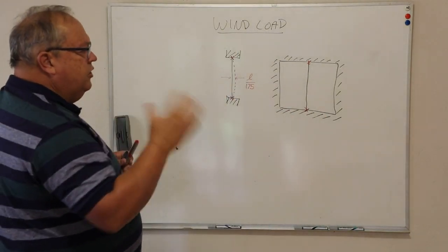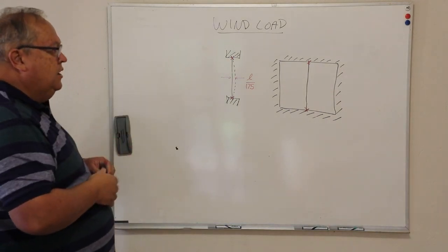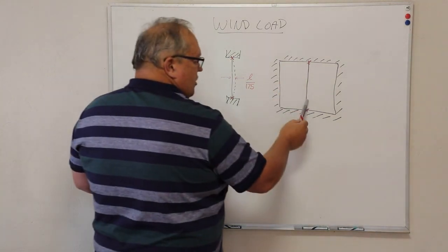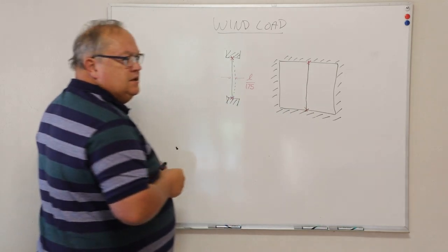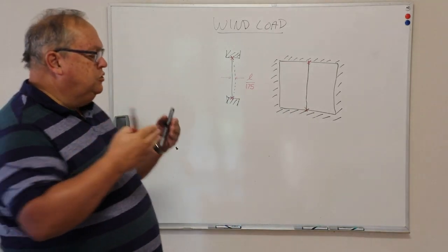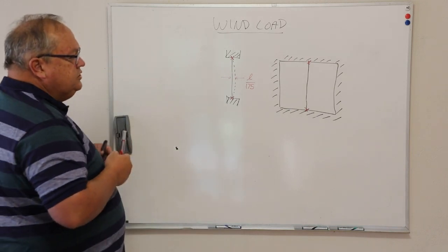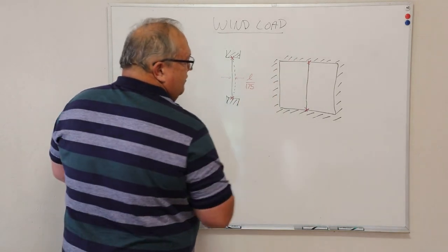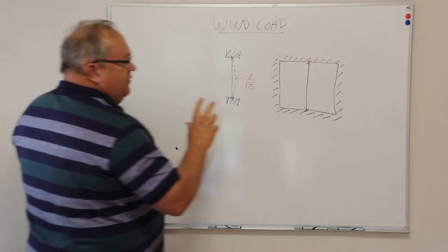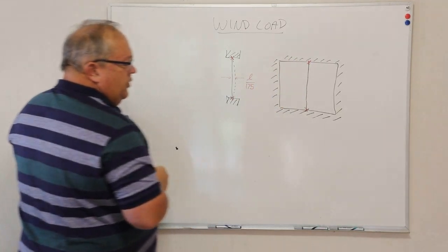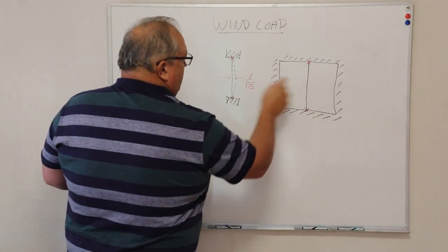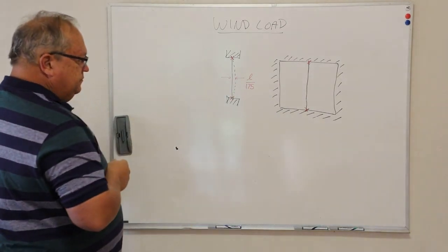Now, this does not only apply for mullions, it would apply for an interlock, it would apply to a meeting style, it would apply to the 2 door styles on, say, a Vistafold where they come together. So any situation where I've got a profile which is supported only at the 2 points, it has to comply with this regulation.